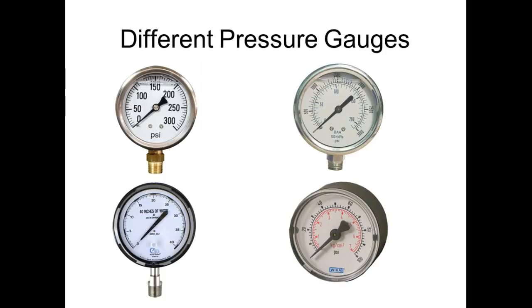So 50 bars would actually be what? About 5 million. We take this and multiply by that, right? It'll be 5,000 kilopascals. So that's going to be about 5 million pascals, right? So pascals is a really, really small unit, and you see why we don't use very many pascals. We use bars a lot because one bar equals 100,000 pascals.